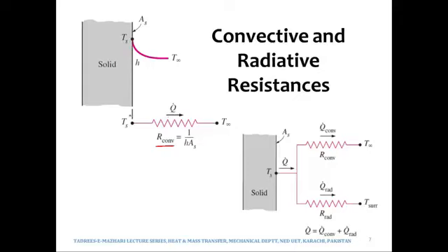What we have at the two nodes are two temperatures, Ts and T infinity, because when we say it is convection we use Q is equal to hA delta T, and that delta T is Ts minus T infinity. So Ts is the temperature of this face, and T infinity is the temperature of the fluid which is on this side of the surface of this face.